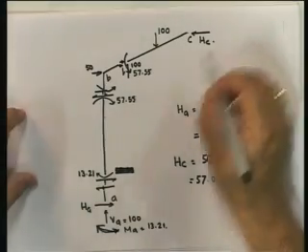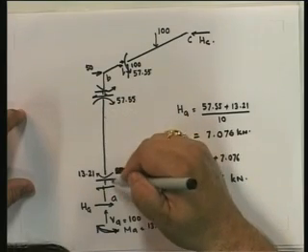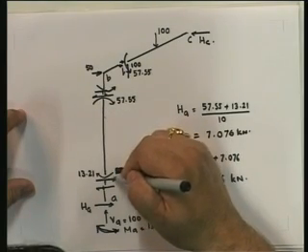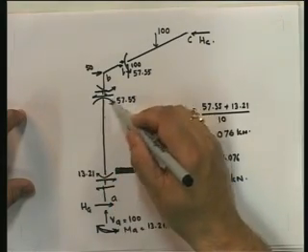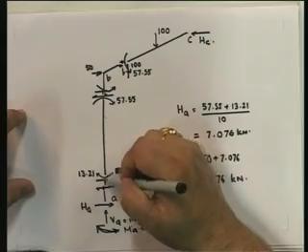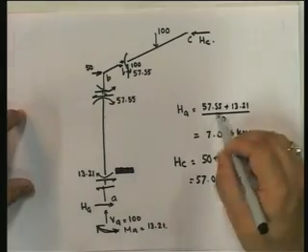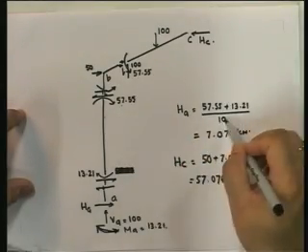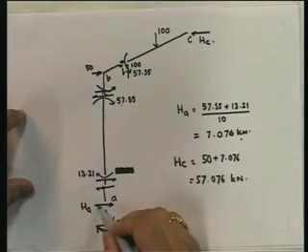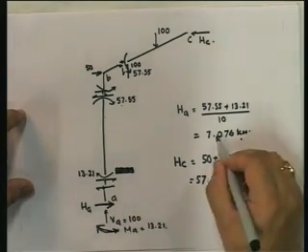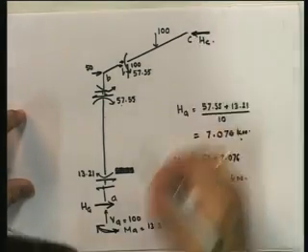Okay, so now from this, if I take MAB, since it doesn't have any loading, the shears at this point are going to be equal to what? This into this is equal to this plus this. So the couple generated by the shear is going to negate this moment, and from that we get that HA is equal to this plus this upon 10. So that's equal to 7.076. So that means HA is in this direction and the value is 7.076.